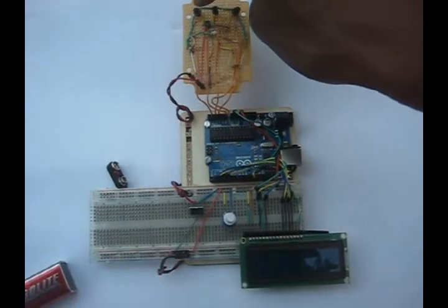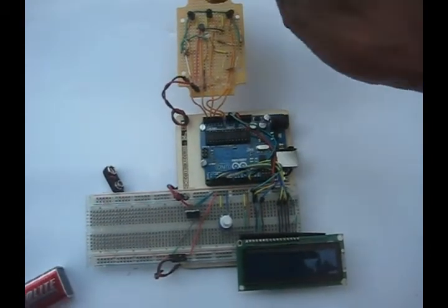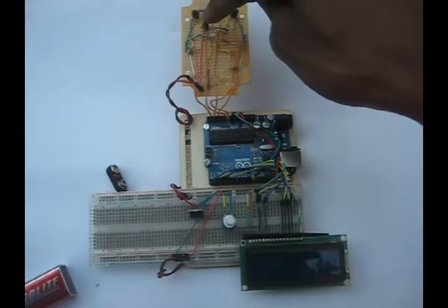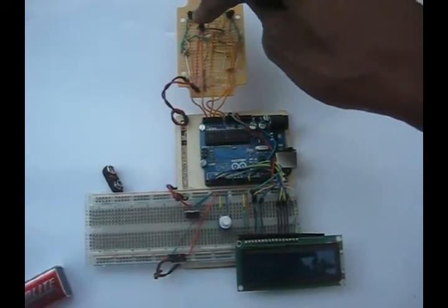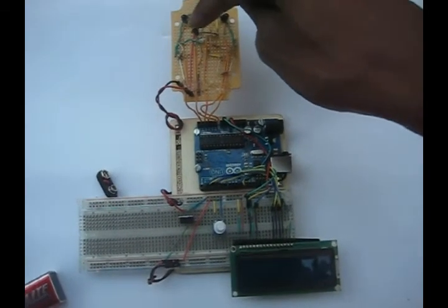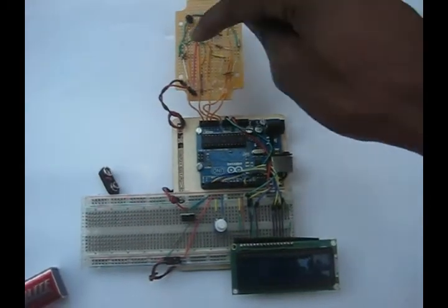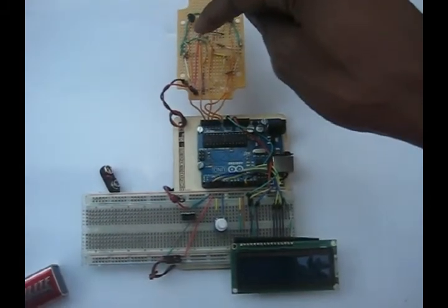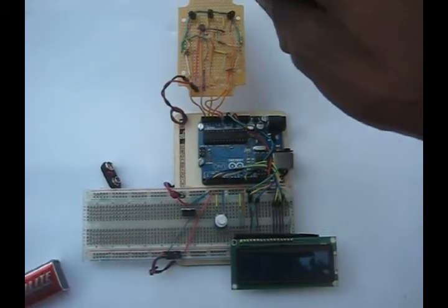I have 3 photodiodes for measuring incoming long wave radiation, and then one temperature sensor that gives the temperature, which with the help of Stefan's law we use to calculate the outgoing long wave radiation. And I do have a phototransistor. This I'm using to obtain the incoming shortwave radiation.